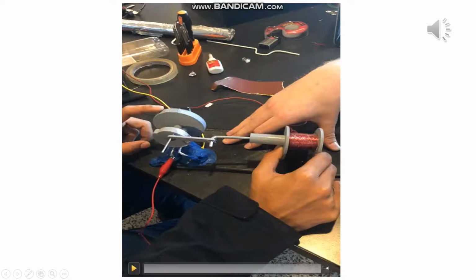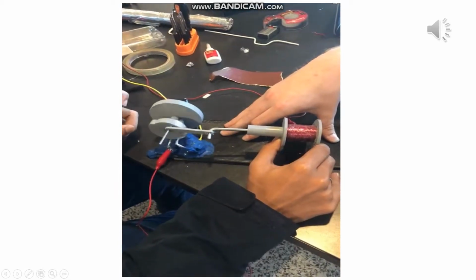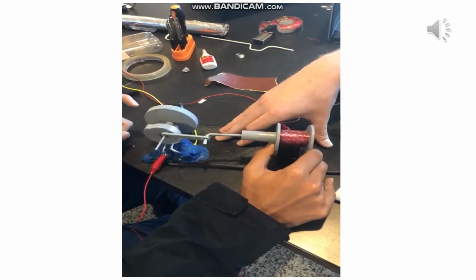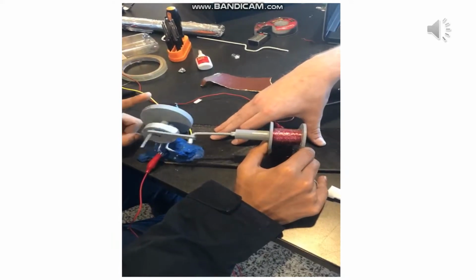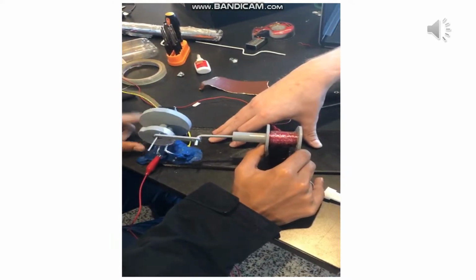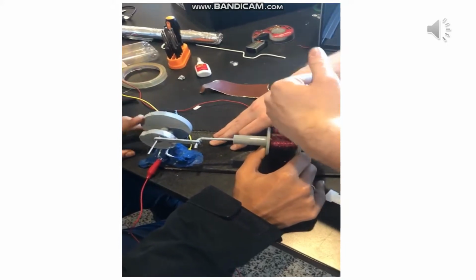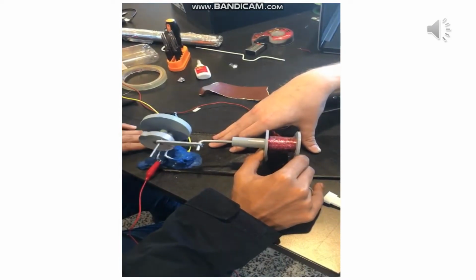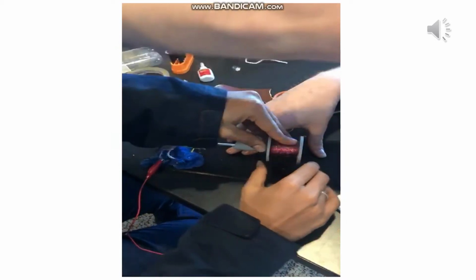The limitation of converting electrical energy into mechanical energy is the loss of energy through the mechanical parts. The biggest one that we faced whilst designing this was the friction between the cam and the switch. Whilst good contact is necessary in order to produce a consistent current to drive the magnets, there is also the possibility that the switch would create a counter torque on the cam, preventing the crankshaft from rotating. This needed to be mitigated by reducing the number of contacts required to produce the current, as well as minimizing the amount of contact time between the cam and the switch.